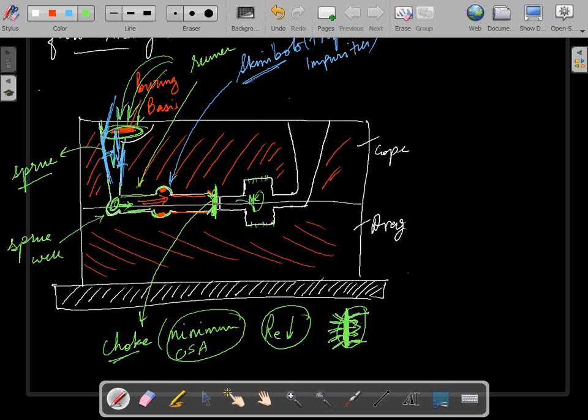Now your molten metal again flows through this runner passage. Now this section, which is just at the entrance to the mold cavity, these are called your gates. Now what is the function of a gate? The function of a gate is to allow the molten metal to enter the mold cavity. This is just a name given to a section. A gate is something through which you enter. So a gate is a section through which the molten metal enters the mold cavity.